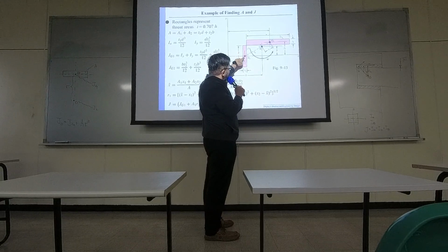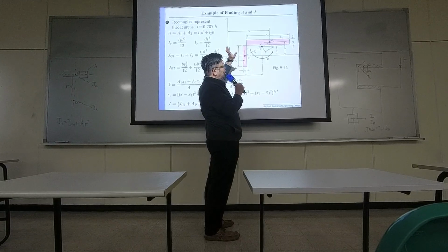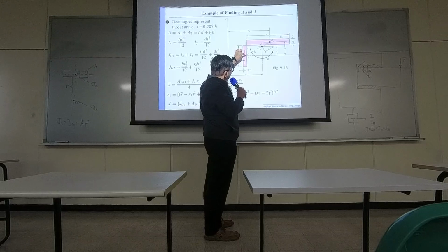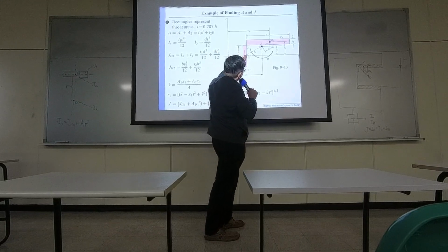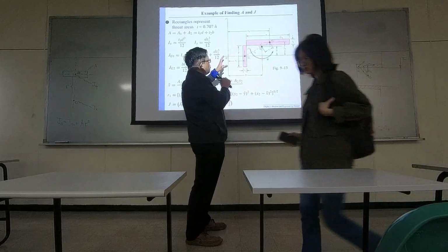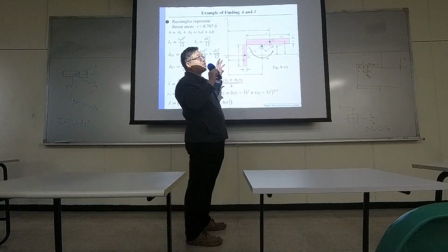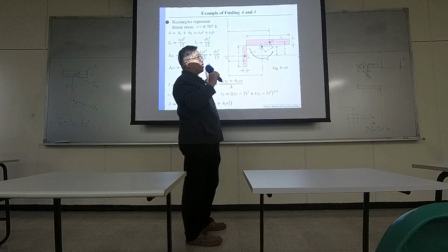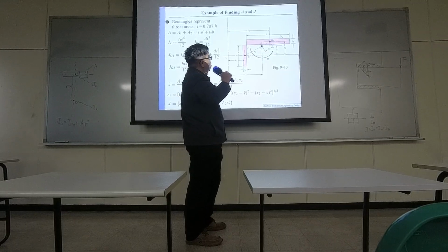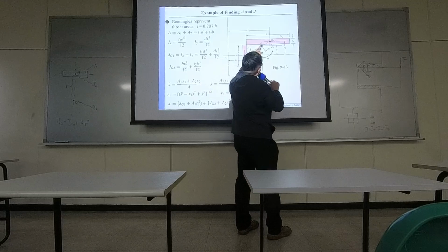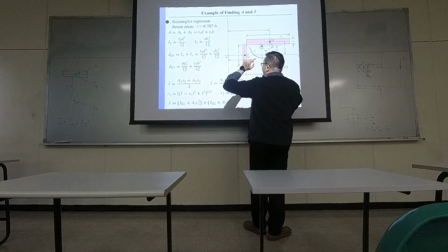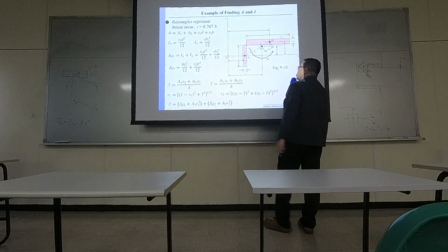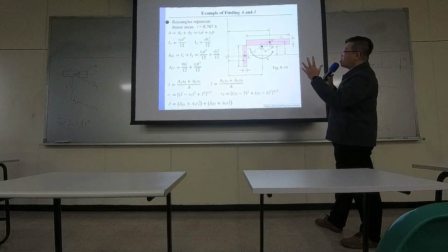JG represents the polar area moment of inertia right at its geometrical center. So you have JG1 and JG2, but you are now combining two shapes together and treating them as one piece. So you have to find their common center of geometry. First, you need to figure out the location of the overall G.